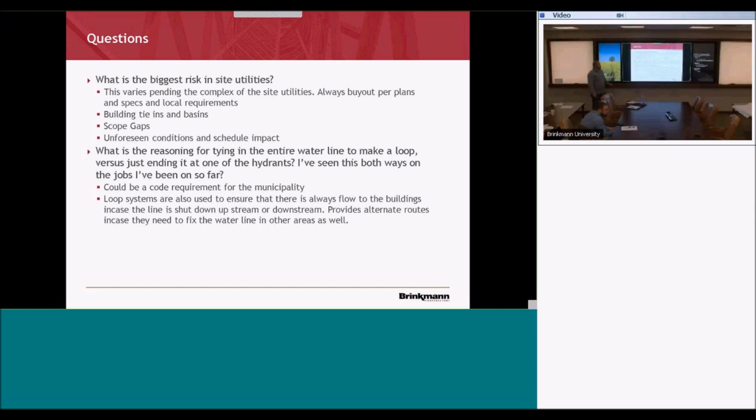On Main Street, Lincoln, we're in a private development called the Firethorn. It's like a golf course and a residential development. They could not locate the sewer main that we were boring underneath. So we basically sent a letter to our owner stating that if we hit it, it wasn't going to be on us because nobody could locate it for us. I don't know how far that would have gone had we hit it, but it didn't hurt to send the letter and cover our tail. In older cities, a lot of stuff's not called out. You have one call, or a state line, that's what they have here.